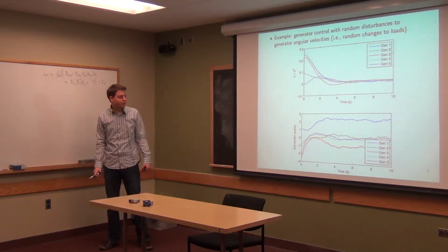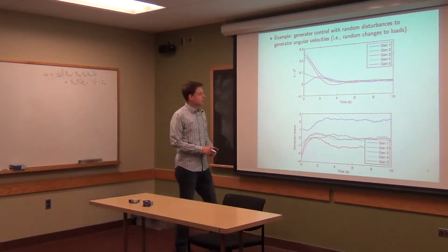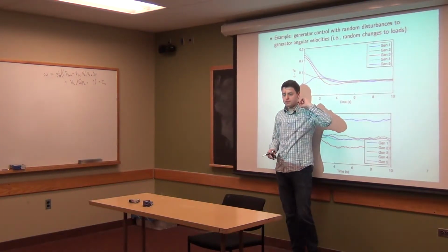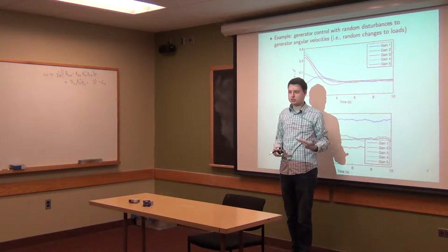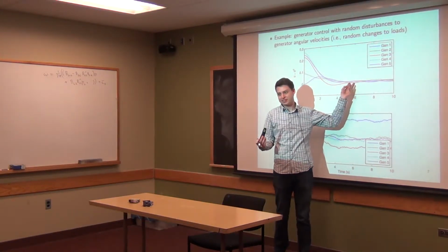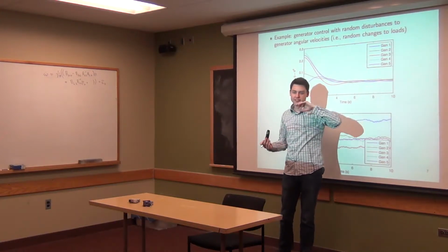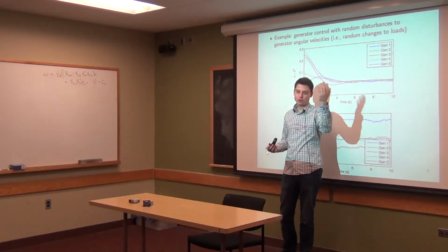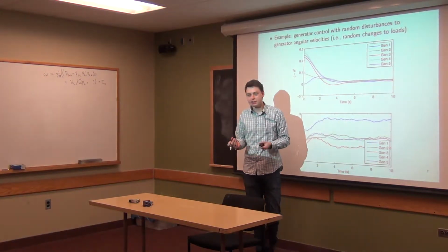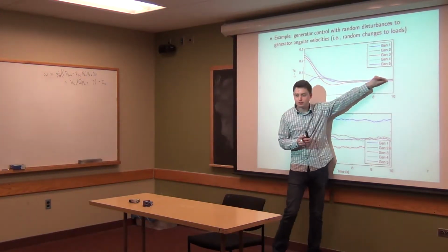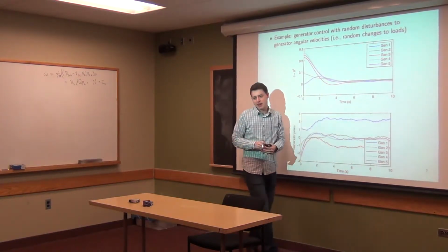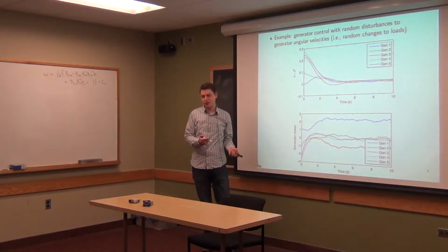Now you might say that, well, this is nice, but I don't really like the fact that it doesn't quite ever get there. And the reality is, in stochastic systems, you have to deal with the fact that the system is never going to quite get to its desired location, right? You can't fix it at 0, because then random noise will push it away from that, and you have to take some action to correct for that, etc. You can push it closer to 0 by using higher control inputs. And that corresponds to higher gains in our LQR controller.